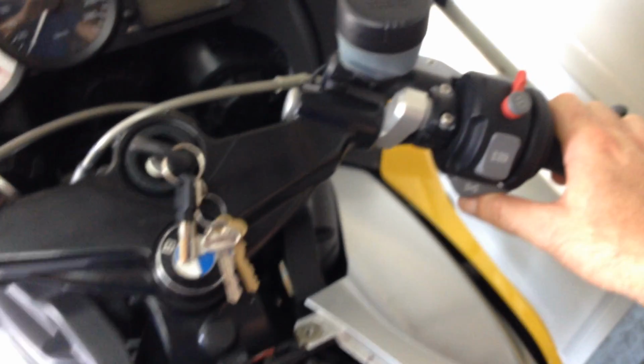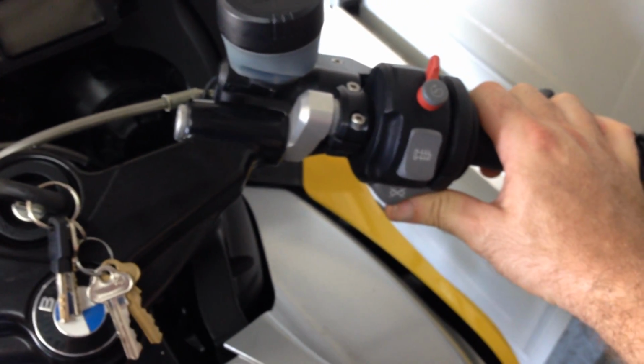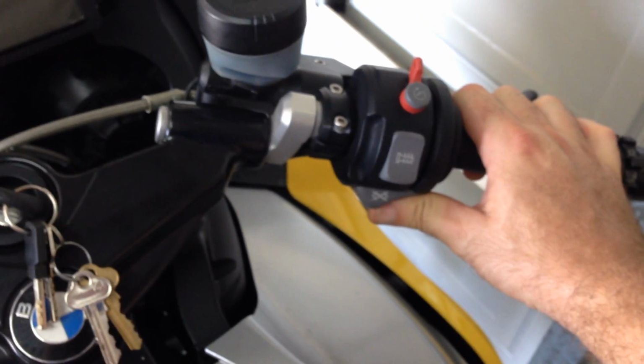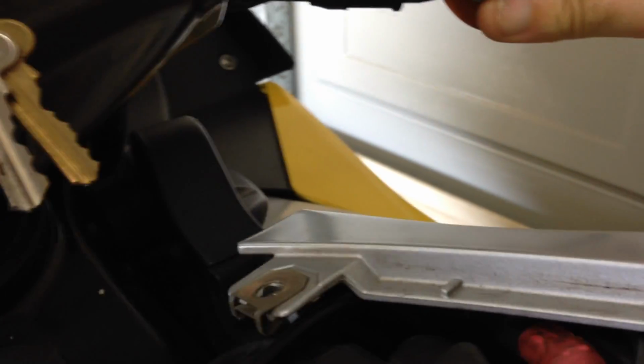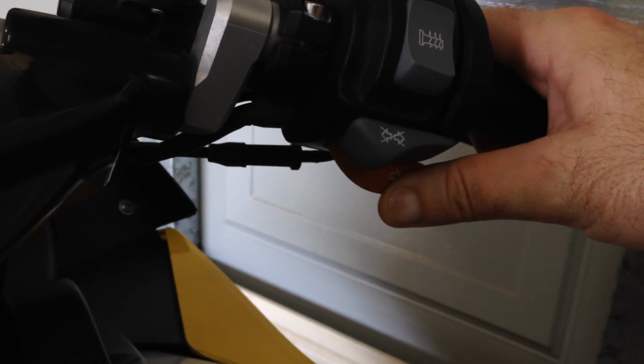So what I do on an 05, you hit the cancel button, hold it for about 3-4 seconds, then immediately switch to your right hand blinker and hold it, and then the low beams will turn off. I've already recoded mine. It's pretty neat because I played so much with the software, I don't have to do this step anymore.